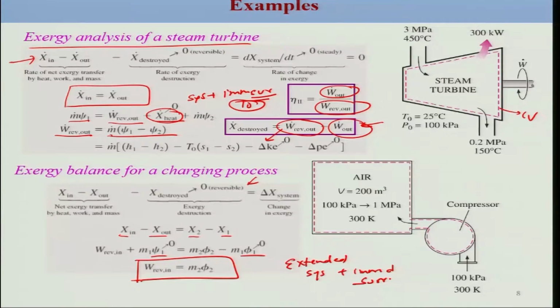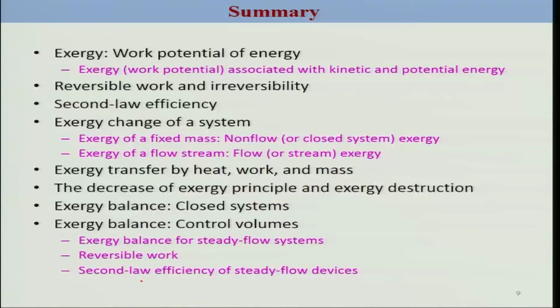Okay. So this is the exercise which we go through, making use of exergy in order to find the maximum or minimum work, and of course making use of other assumptions. If it is air, we are going to make use of ideal gas, and thus we can calculate your minimum or maximum work, and doing so we can also evaluate second law efficiency based on exergy information. Okay, so this would be the end of this particular topic.